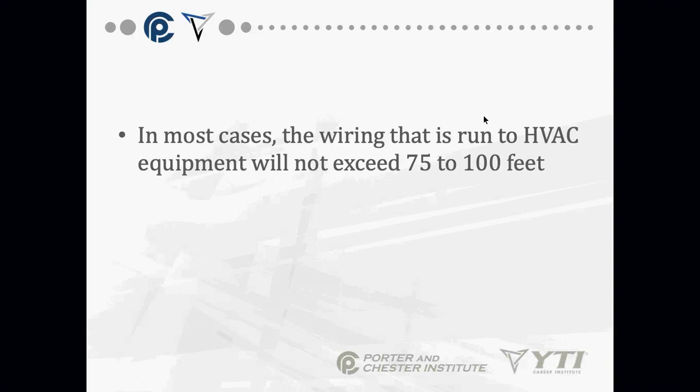Okay, but is that the length I'm talking about? Yeah, it's a combined length of everything. Basically, what I'm talking about is the length of the wire. So the wire goes up into the attic through the wall behind the breaker panel. It then runs to the back of the house, comes out to a disconnect, and runs back to the air conditioner.